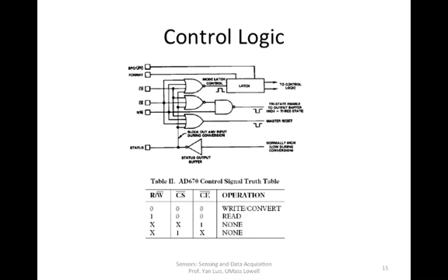By the way, these pictures and tables are coming from the datasheet. When you work with any IC chips, you need to get access to the datasheet. Same for the PIC microcontroller you're going to program. You need to get the datasheet. Right? That is the Bible for the chip. It tells you everything about the chip: how to program it, how to connect it, and if anything goes wrong, how you troubleshoot.